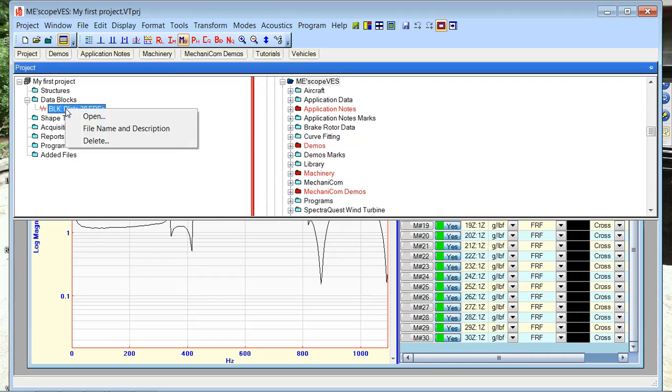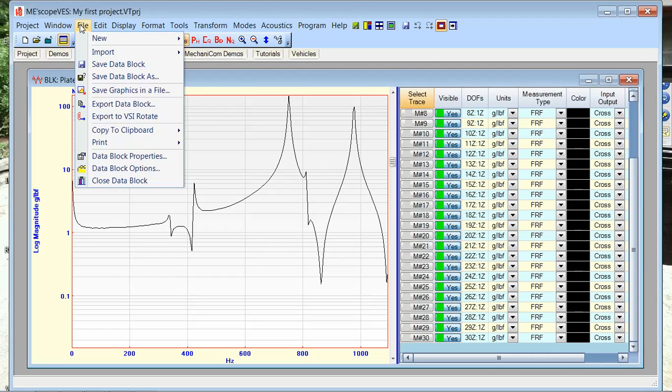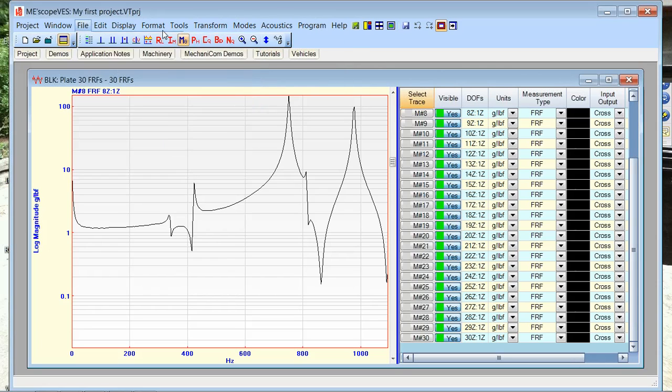Well, let's go down here under the Draw menu. Again, the Draw menu is the same as this one up here, but I'm going to take it off of the right-click menu, and down here under the Draw menu is something called the Drawing Assistant. So I'm going to open that, and you can see the drawing window changed now, and over on the right I have a tab that says Substructure. So what this Drawing Assistant allows us to do is build models by manipulating substructures. And this is a list of them.